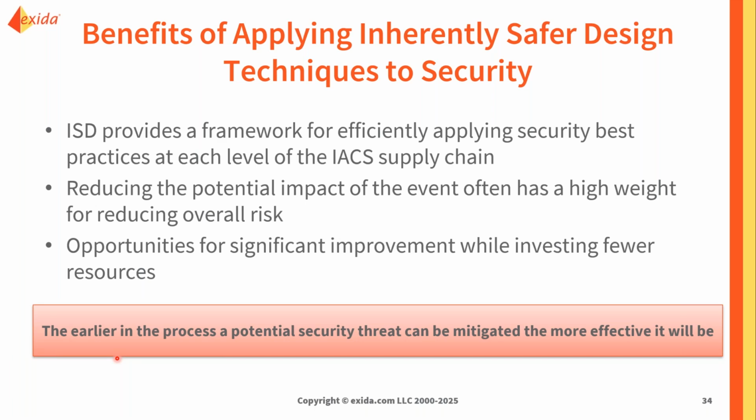And again, depending on the risk for the site, different designs may be appropriate. It's not that there's a single design or that going to a non-hackable protection is always the right decision. But we do need to understand the hazards and risks associated with our specific context. And depending on those levels, pick the controls that are most effective to get us to a tolerable risk position.